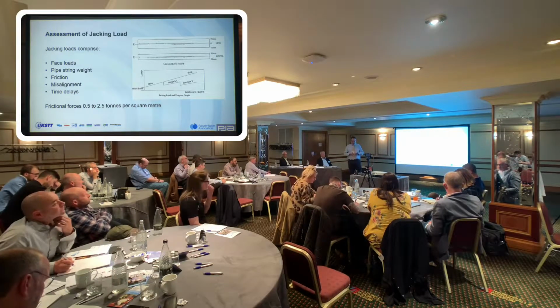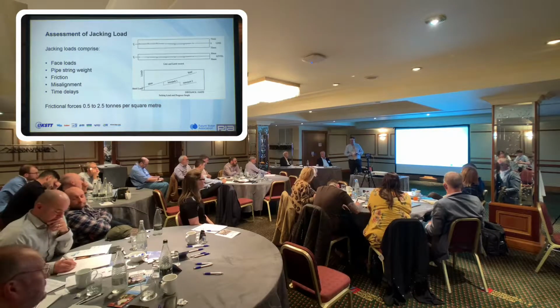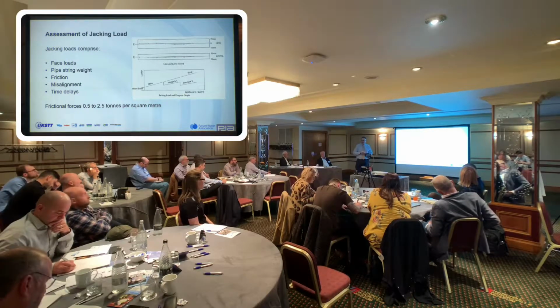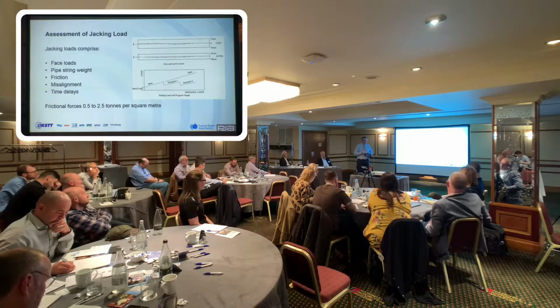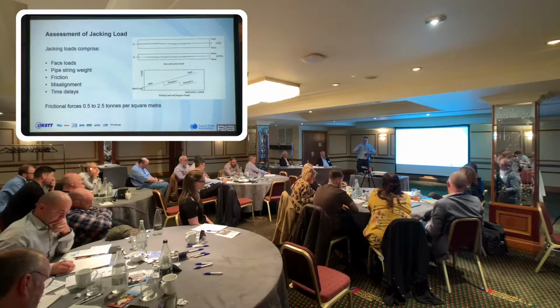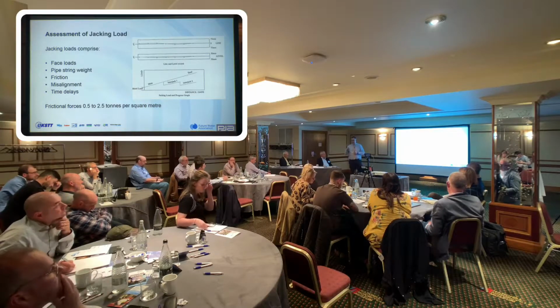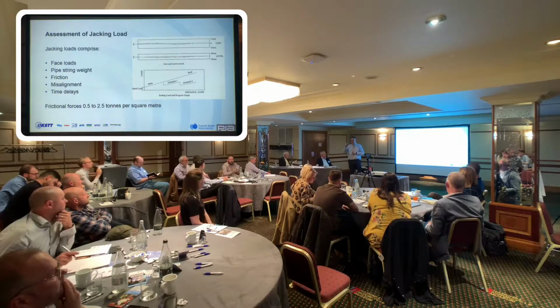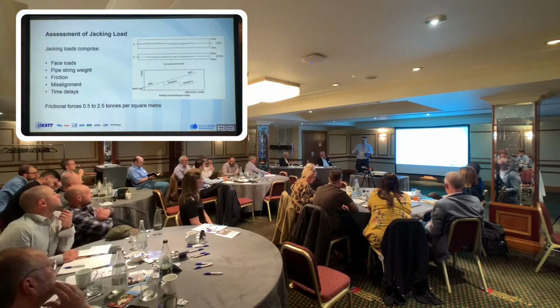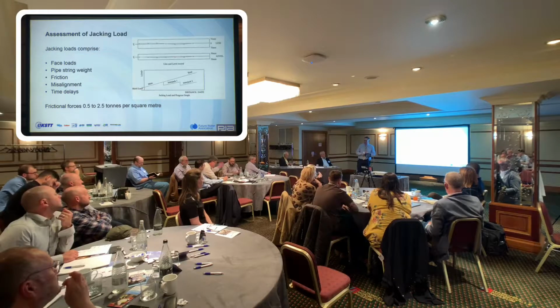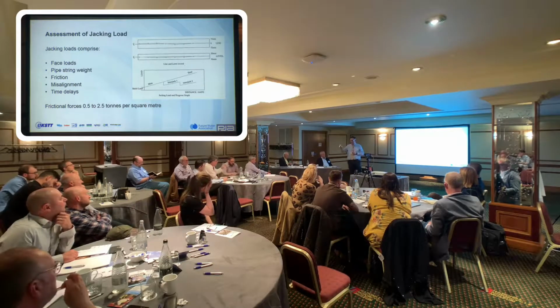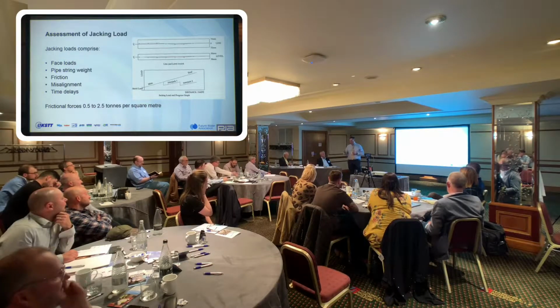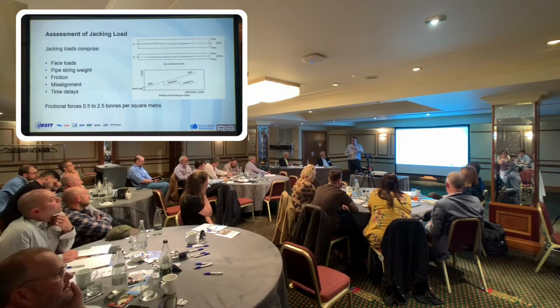Throughout the document that we're going to talk about, there was a lot of research done by a chap called Haslam at Liverpool University, and he looked at various ways. So he looked at a stable bore with the pipe theoretically floating in this medium of lubricant. So in other words, you cut the hole and you pressurise the annulus and the pipe has effectively got no load. Interestingly, when Graham showed the graph earlier on of one of his drives where there was hardly any load whatsoever, that's the kind of evidence that might suggest you've almost reached that kind of state.